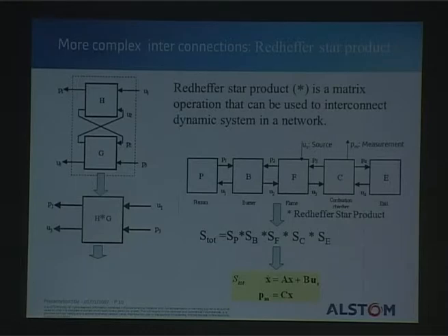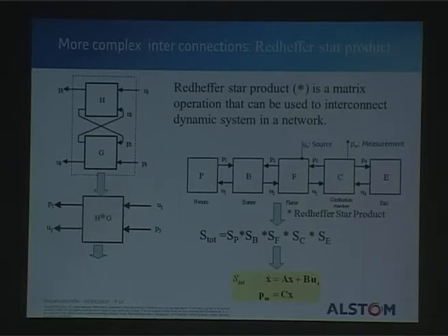And at the end, you get, again, a very simple equation with some state equations. This is the time derivative of the state. It gets updated by the state, multiplied by some matrix A, where all this information is compacted together, as a response to some source terms. And this Us would always be the source to the system, so really the physical source driving the system. That can be turbulent combustion noise typically.